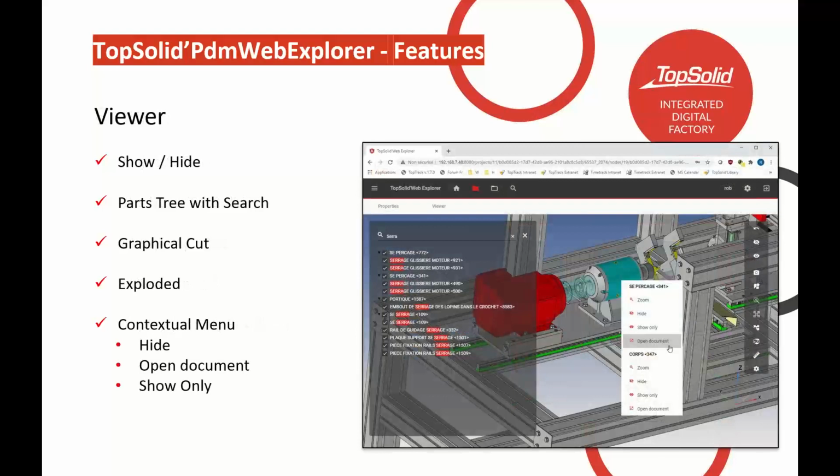From there, you have the viewer itself. Once you're in the viewer, you can show and hide any element you want. You have your entities tree, so you can show or hide objects through the entities tree. You have the graphical cut as well, so you can make dynamic cross sections and dynamic exploded views. You have your contextual menu, the right-click menu, that gives you the ability to hide open documents, show only, so you can really drill into your assemblies like you would naturally inside of TopSolid anyway.